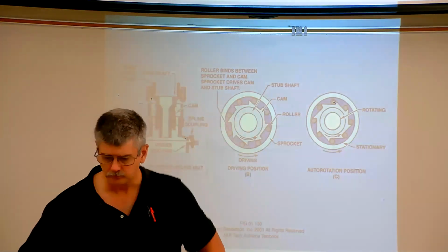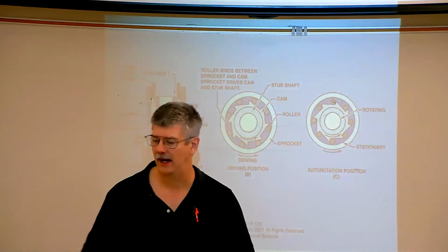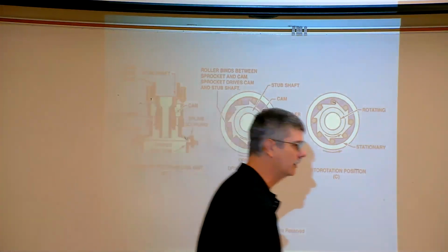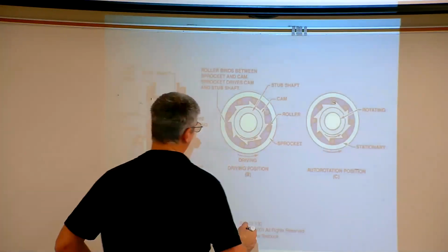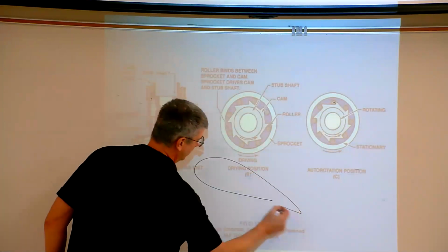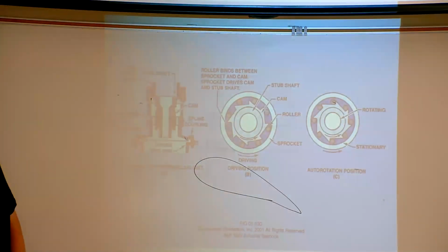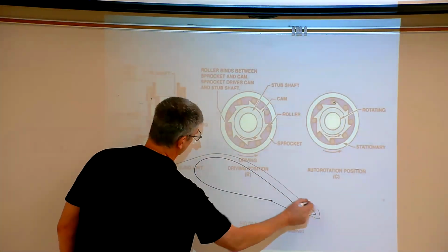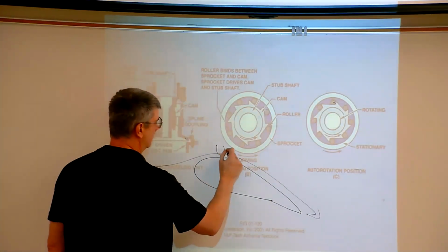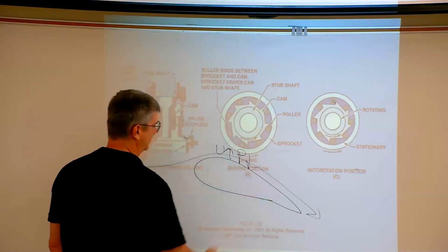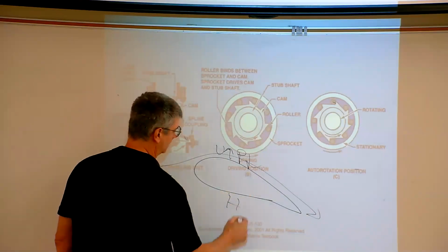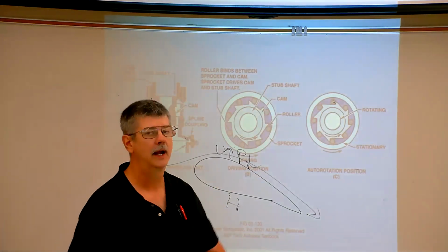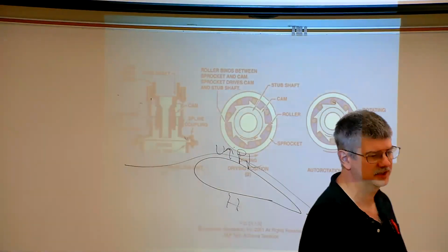Okay. We talked about the asymmetrical airfoil being the airfoil that is used the most, right? And we came up with a very basic idea of how the airfoil produces lift. As air flows over, we say the velocity increases and the pressure decreases. Underneath, we have a relatively high pressure, high goes to low and lifts the aircraft up. And that's a very simple way to explain it.